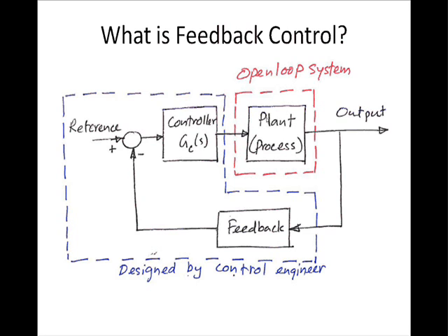let's say we got a power amplifier and a DC motor in combination can be the open loop process, and then we are after the speed of the DC motor shaft. So that is our output, and the process input then is the input signal to the power amplifier. Then if you want to introduce a feedback control system around this open loop process, what we do is we measure the output. If it is a motor speed, then typically we use a tacho generator or an incremental encoder to measure the output speed.